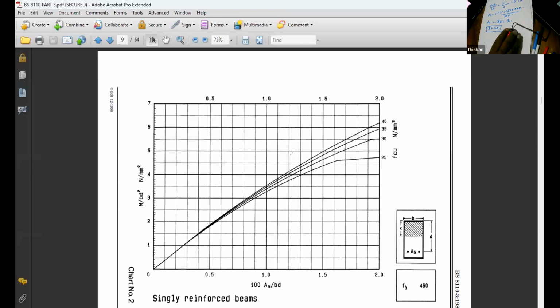And for most of the single reinforced beams, grade of concrete does not matter. So there's no point in using any concrete stronger than 30 megapascal in a slab, because in the slab we cast the beams together. So never ever use anything more than 30 megapascal in a slab. That's the theory. That's how I design, so that's how you get very economical designs. I never use anything more than 30 megapascal in a slab.